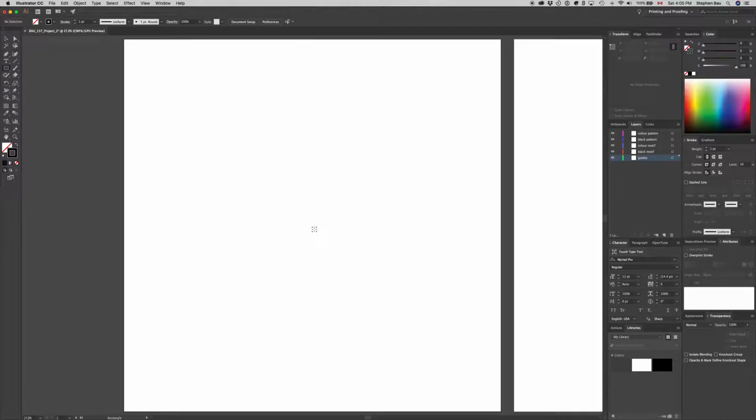So I'm just going to option click right in the center of the document or the artboard, and the rectangle will be 100 by 100. So type in 100, tab 100, and then click OK. Great. So if I want that rectangle to be exactly in the center, I can change my x and y coordinates. So the x would be 300, half of 600, and the y would be 300.